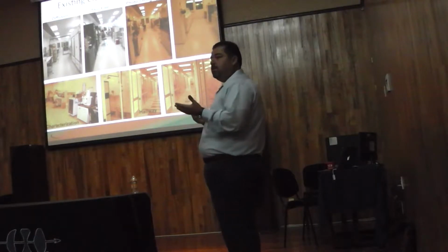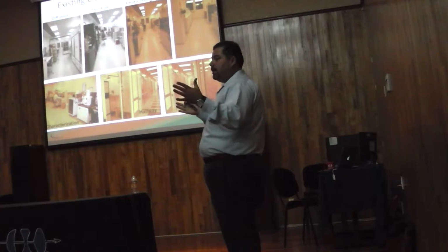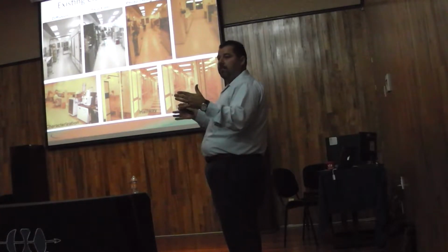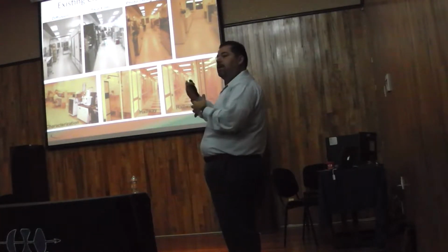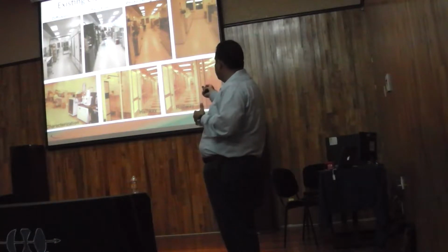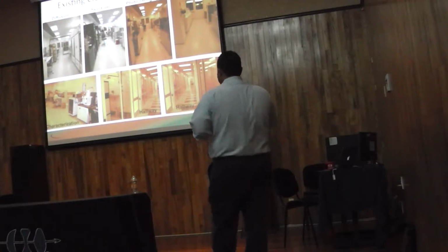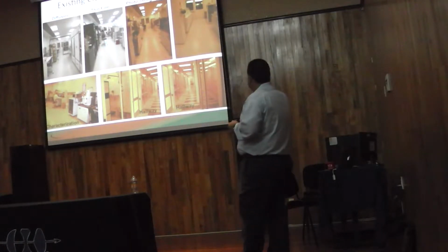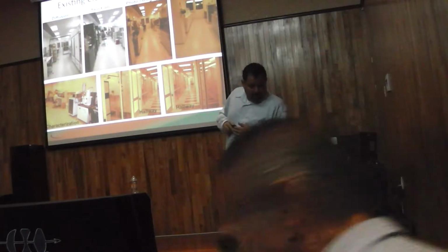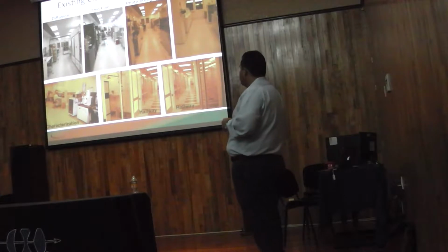And what is nice about having these kind of tools is that I can have an idea about a device on paper, and then we can go and write that mask in the mask writer, and then they can start making the device. Okay, probably within a couple of days you can start actually fabricating devices. We have surface preparation for regular wet etching of the material we deposit.